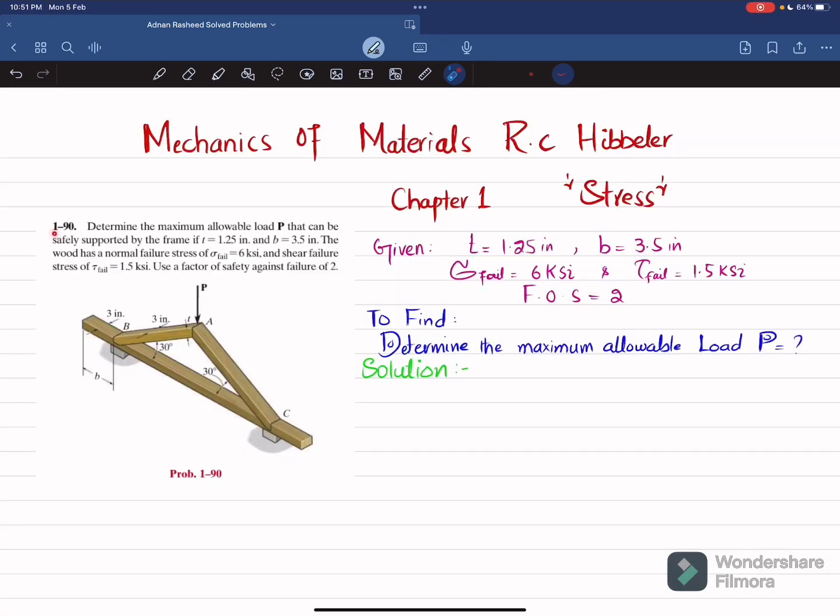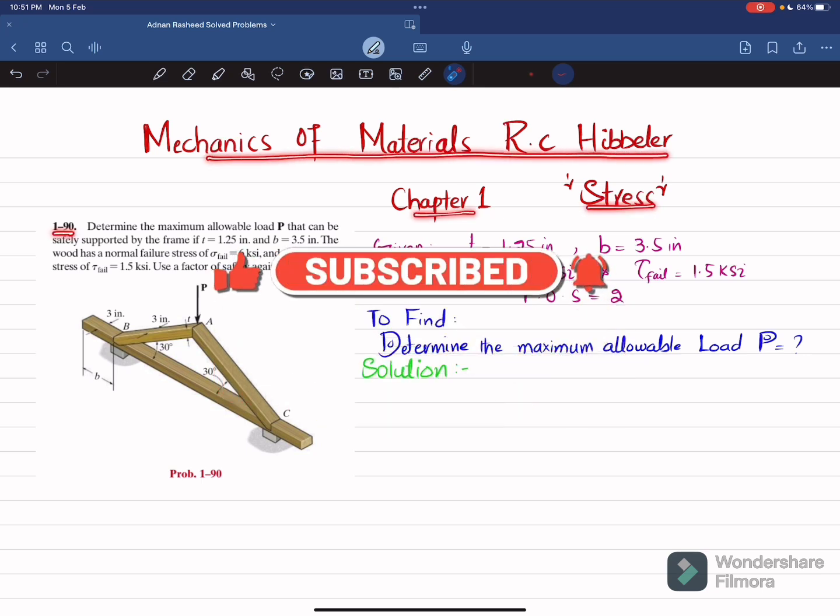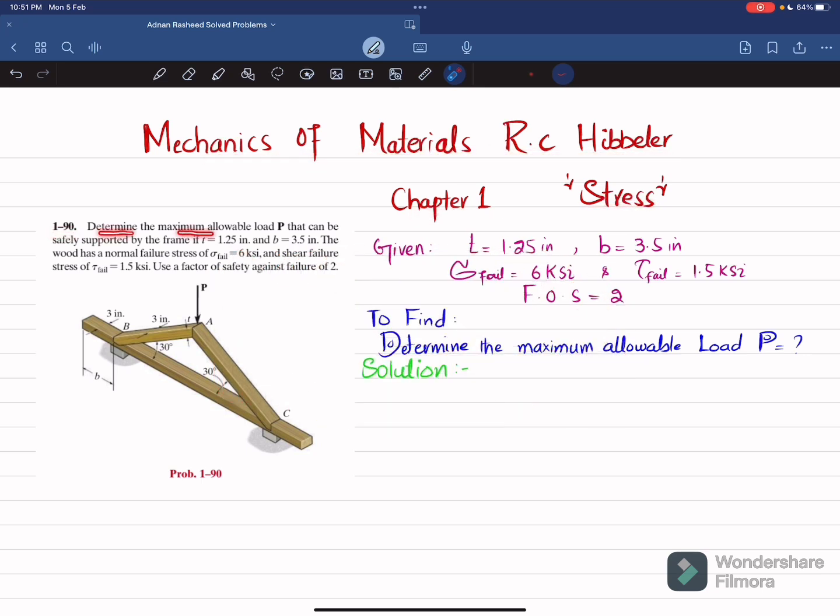Welcome back. Problem 1-90. This problem is taken from chapter number 1, stress, and the book name is Mechanics of Materials by R.C. Hibbeler. The statement is: determine the maximum allowable load P that can be safely supported by the frame if T is 1.25 inch, B is 3.5 inch. The wood has a normal failure stress of 6 ksi and a shear failure stress of 1.5 ksi. Use a factor of safety against failure of 2.